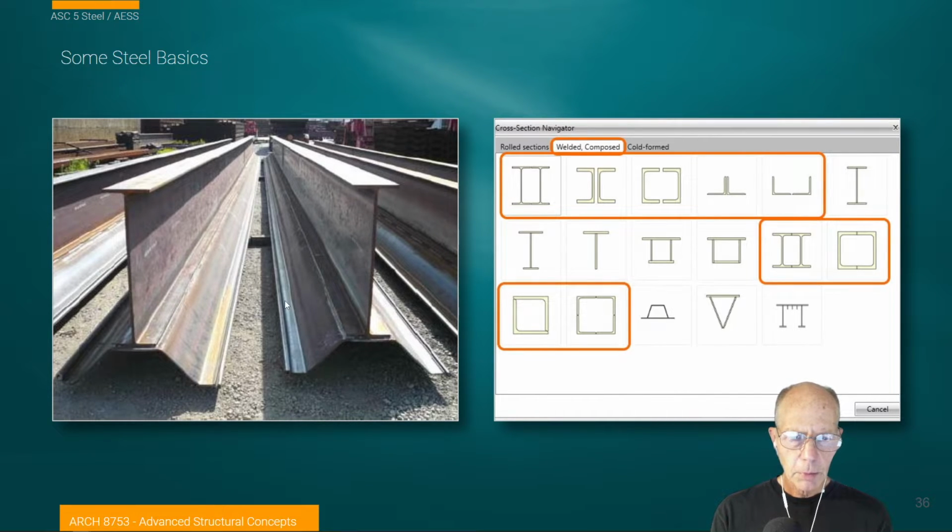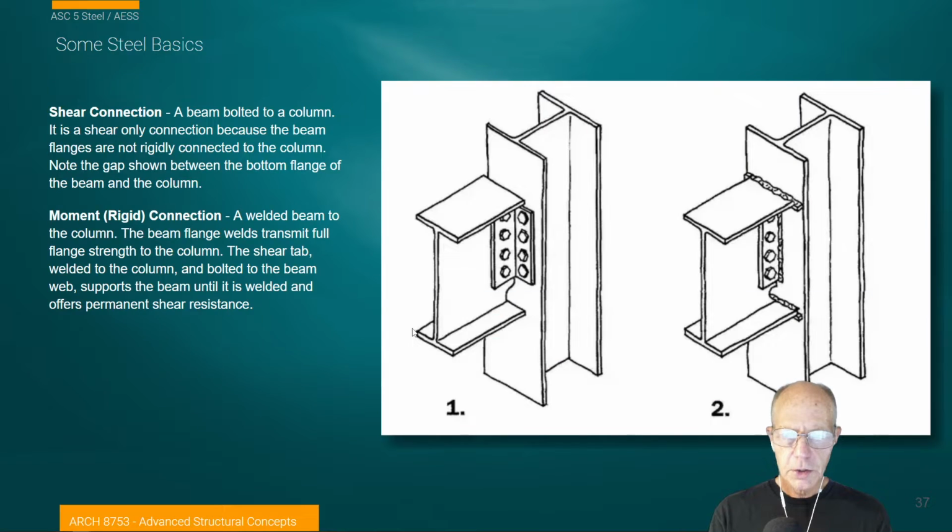I said caissons, but I really meant piles, to resist soil from infilling and excavation, many times to create a load-bearing surface for a building, all kinds of host of applications. And when they're really long, they may have issues with them having actually to support so much load that they need to be reinforced. So in this case, an I-beam has been welded to them, so that is a built-up section. But mostly for our interest, we're concerned with this idea of being able to build up these sections specifically to kind of the decorative and performance issues that we're looking for as architects on our projects.